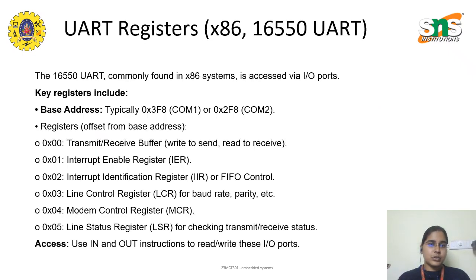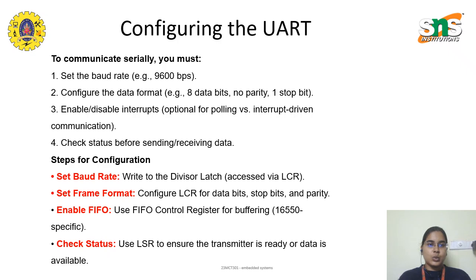And apart from that, you have UART registers. Yes, we have base registers, typically 8-bit, and each register has transmitting and receiving buffers, interrupt enabling registers, modem control, etc. These are mainly used for reading and writing the input data in the output peripherals. And for configuring the UART, the main steps to focus on are baud rate, frame format, FIFO, which is used for buffering purposes, and checking the status signals.